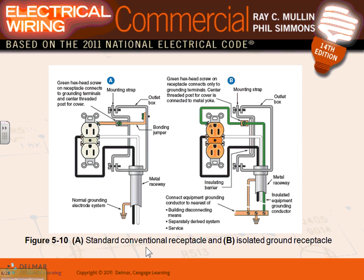One is a fully isolated green conductor for grounding the receptacle, and the other is the shield of the MC or AC cable, which will be used to ground the metallic box as well as the ears and the frame of the receptacle. Any questions, guys? Most of the hospitals, and most of the applications that they specify, will have two.